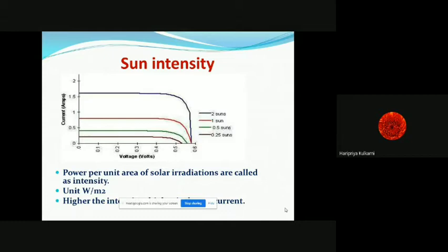So even on an extremely overcast day, it can produce up to 30% of the power. One more important aspect is that solar panels are designed in such a way that snow does not get collected on the module because we provide a tilt angle to them. So snow is not accumulated, but automatically falls down to catch the sun angle. Mechanically also, modules are designed so sturdily that they withstand golf-size hail.